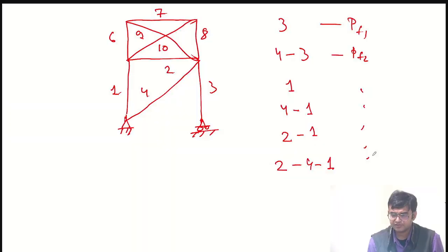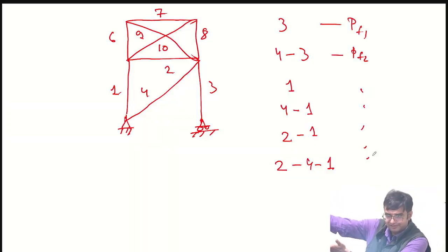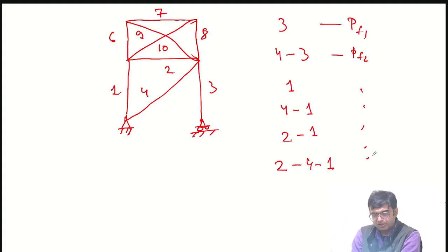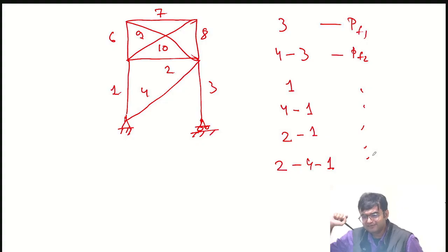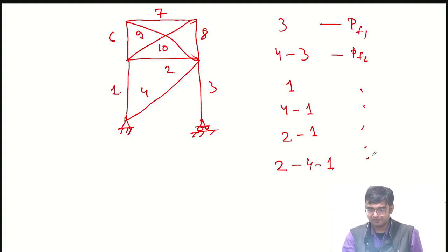Because then, even if that probability of failure is a little bit higher, because there is a chain, when one thing fails, you get a warning. Because warning is also important. Now, to continue on this, each of these will give you a probability of failure, right? Whatever is the maximum probability of failure out of this is your probability of failure of the system. So this is what you will do in the fault tree approach.